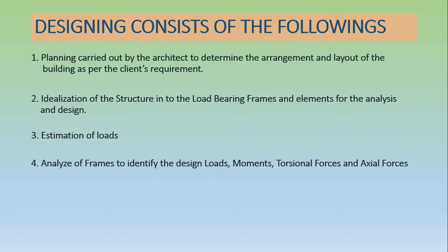According to that, you have to analyze those frames by using linear elastic methods, and you can use the moment distribution method to calculate end moments. Then according to that you can have bending moment diagrams, and then bending moment envelopes.